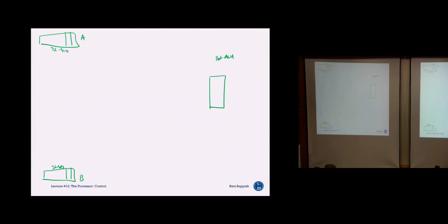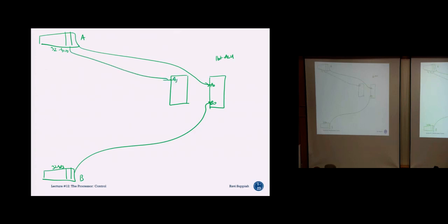So what will happen? The bit 0 will come here, A0, and B0 will come here. When I supply A0 and B0 to this bit, similarly, I have the next 1-bit ALU. This is from the next bit, which is your A1, and this is from the next bit, which is your B1. So inside the ALU, you have 32 1-bit ALUs stacked together.